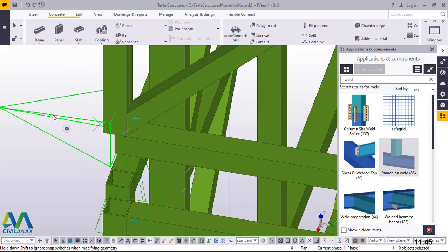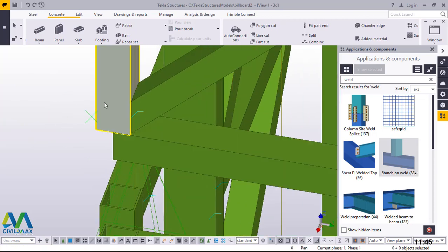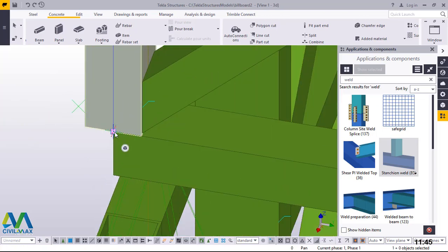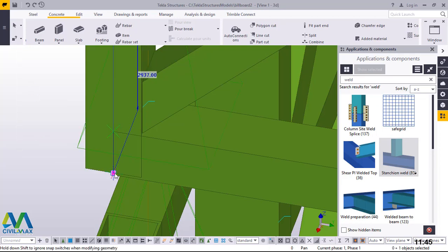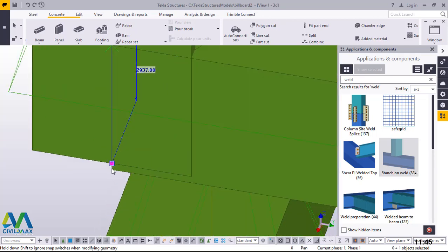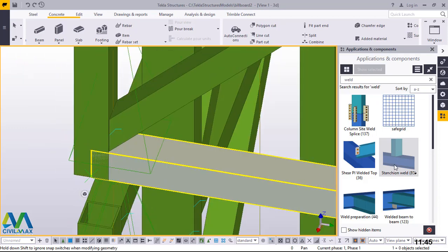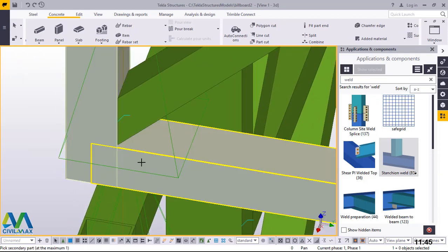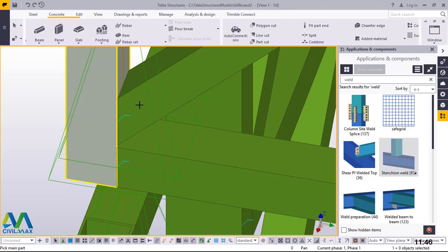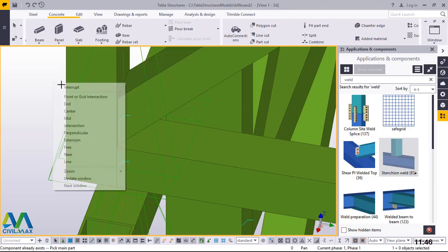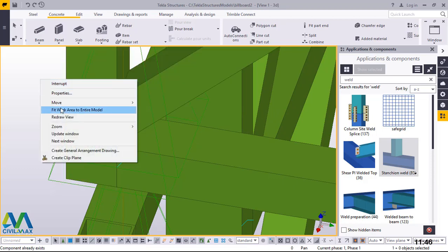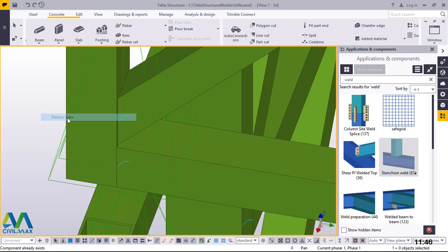and we'll delete that weld. It's not a hectic thing to do, but the way I'm doing it, I want you to interact with this comfortably so that you'll be comfortably using these Tekla structures. Perfect. That's okay. I'll come here and do that and connect with that. Do that and connect that with that. When you hear the bell, it means a similar connection already exists. So just redraw.